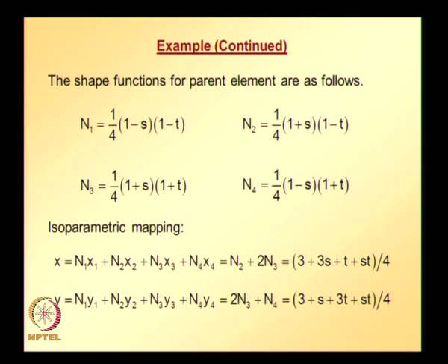Similarly, y is equal to n1 y1 plus n2 y2 plus n3 y3 plus n4 y4, where n1 to n4 are the parent element shape functions, and y1 to y4 are the actual element nodal coordinates. Substituting this information, we get the relationship between y and S and T.